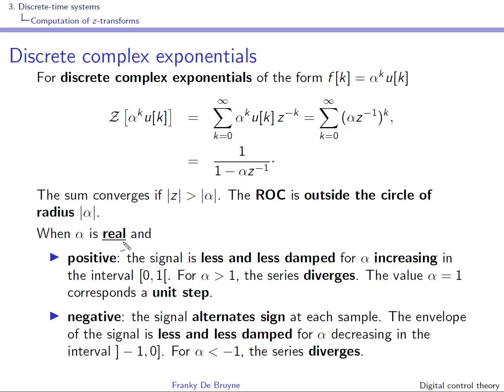In this case we will take alpha real and negative, so we can still obtain a different expression of the z-transform if you use the variable z. We'll again show the z-domain with the unit circle, modulus of z equal to 1, and in this case we'll take alpha negative. So we'll consider a case here at minus 0.5, so alpha is equal to minus 0.5, and we'll consider a case where alpha is negative but its modulus is larger than 1. So you're outside the unit circle, and you can imagine that this will lead to a sequence that is unstable, diverging.